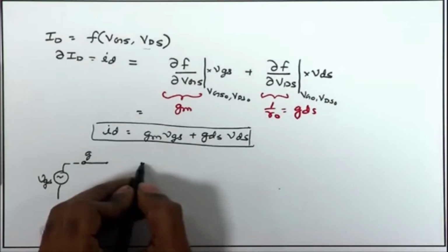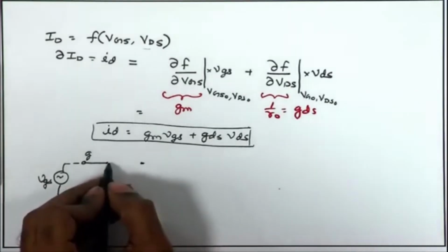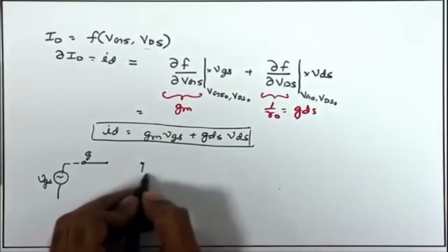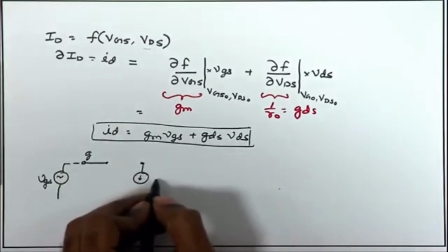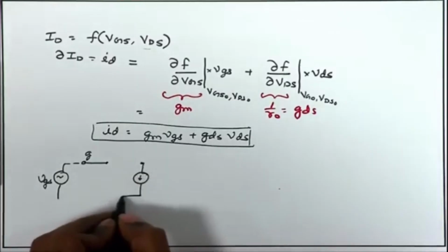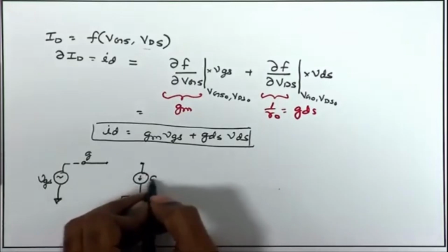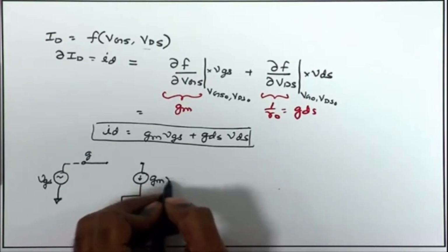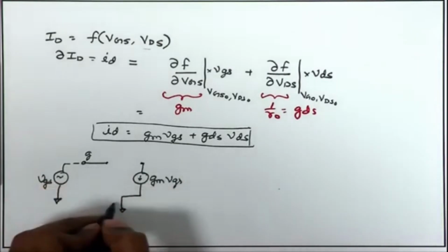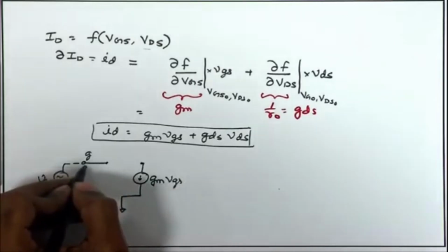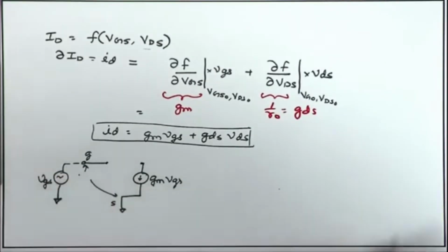Between the drain and the gate you do not have any physical connection ideally, because it is isolated using an oxide, and then you have a small signal current flowing between the source and the drain, that is GM times VGS, because of the signal appearing between the gate and the source.